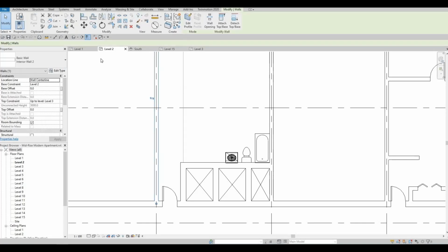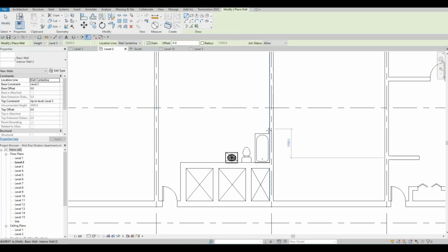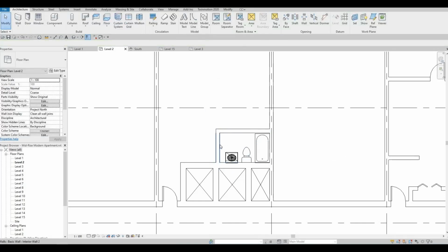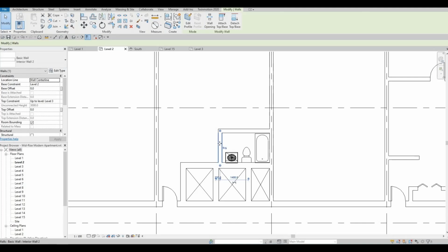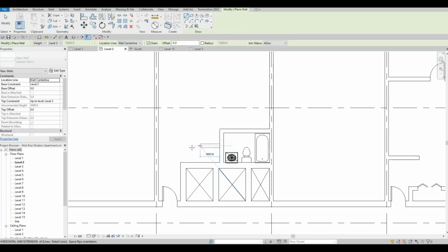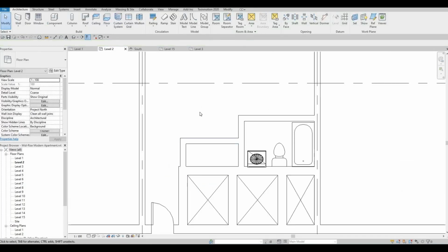Now let's add in our wall. So wall number 2, and then type in CS to create similar. And then CS again for the closet. Type in AL to align. Let's align this wall to this wall.